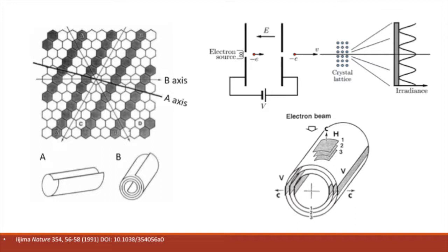To test which orientation the nanotubes were in, the researchers used electron diffraction analysis. This basically works by firing an electron beam at your sample, where the electrons will interact with the sample atom's electron cloud or hit the atom's nucleus and get scattered. This produces symmetrical dot patterns that can ultimately be analyzed to determine the crystal array of your sample.